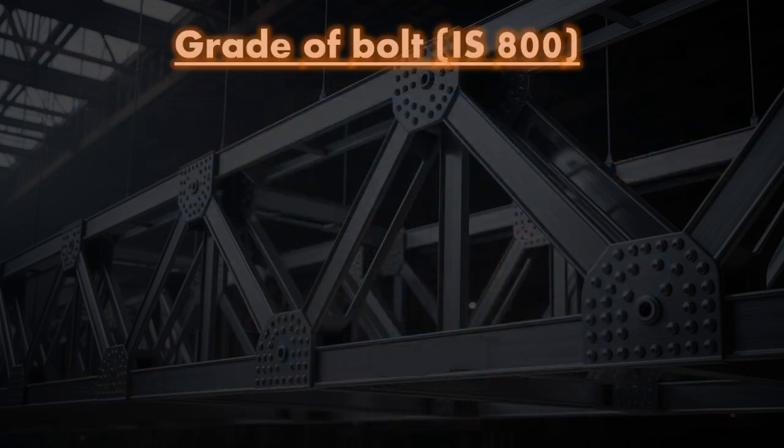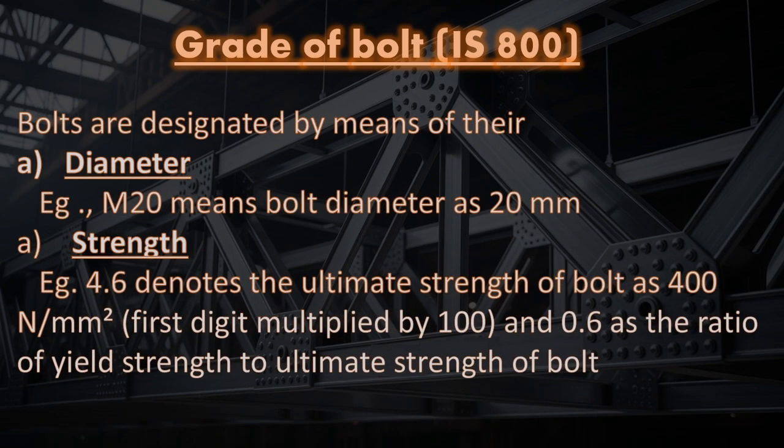Grade of bolt, Indian Standard 800. Bolts are designated by means of their 1. Diameter. Example, M20 means bolt diameter as 20 millimeters. And 2. Strength. Example, 4.6 denotes the ultimate strength of bolt as 400 Newton per square mm. First digit multiplied by 100, and 0.6 as the ratio of yield strength to ultimate strength of bolt.